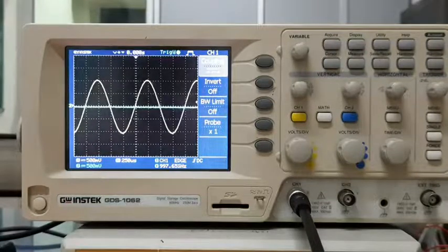So this is another important point to keep in mind, that if by doing all those previous things, amplitude scale, time scale, trigger level, trigger channel, with all this you still don't see the signal, then maybe look for the coupling, and you might find that the coupling is not set according to the signal, so change to that. And normally a DC coupling is the best to start with, unless you want to filter out the DC component of a given signal, right? So we'll touch upon that later. So that is another important thing.